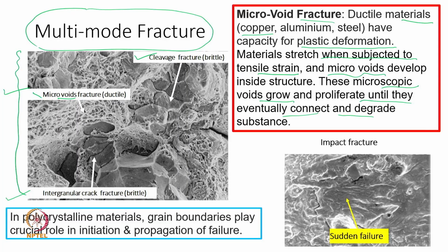Now, sometimes a dimple of bigger size looks like a crater, which has been shown in this case, but this crater is really a little bigger than the dimple or microvoids. In this case, it really requires much more energy, like a sudden failure. It is like a big ball impacting the surface, and a cavity or depression or deformation is created.